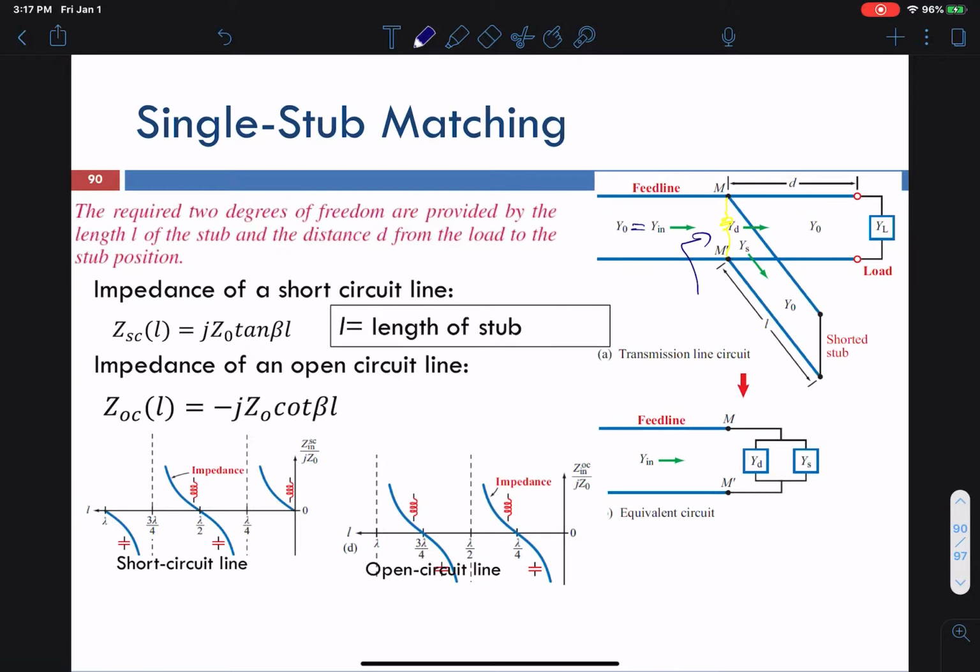Also, a few classes back we discussed that your short circuit stub or open circuit stub could be either inductive or capacitive based on their length. Look here, this is the open circuit stub. For the first 0 to quarter wavelength, they're capacitive, then inductive, and alternating. And this one here, the short circuit stub, is inductive for the first quarter wavelength, then capacitive, and it goes back and forth. That's because of these two equations we discussed in previous chapters, right?